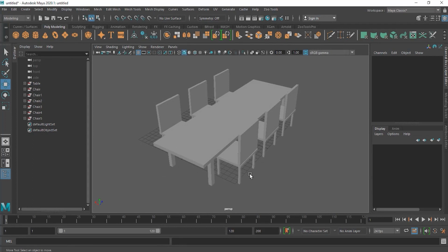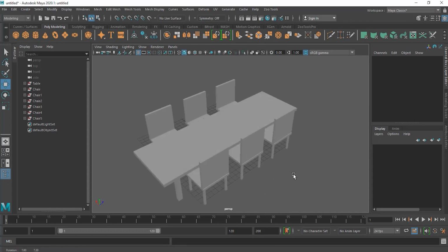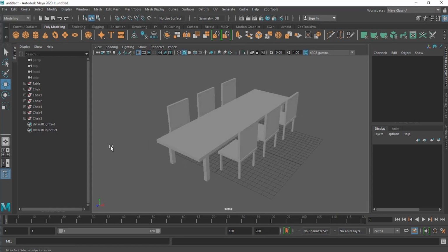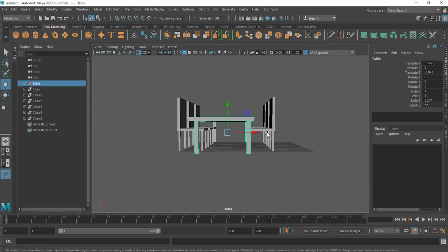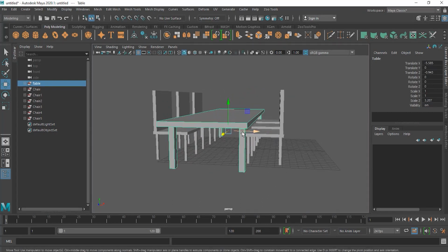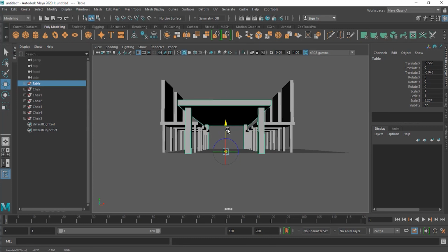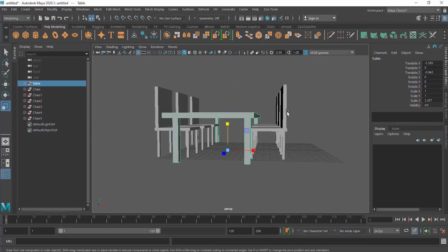Okay, now the last thing, when you're moving anything, you can do the snapping. Now what is the snapping basically? Suppose I take my chair and let me do one thing. Let me press D on my keyboard and move the pivot down on the ground, so it will stay on the ground rather than in the center, otherwise it will not be that good. Okay, so now it's on the ground, so anything that I change will be from the ground itself. So it will stay like that.